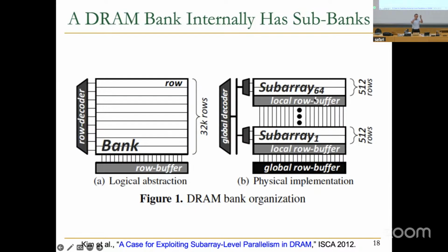And then you have bigger interconnects that are not exactly shown here. Actually, they're shown kind of here, but it's not actually a very accurate picture. I'll show you better pictures soon. Essentially, you have bigger interconnects that drive the data out of the chip. So you bring the entire row into a smaller array, a subarray over here, a smaller local row buffer. And then if you want to access a column, there are bigger interconnects over there. That's just for you to think about.